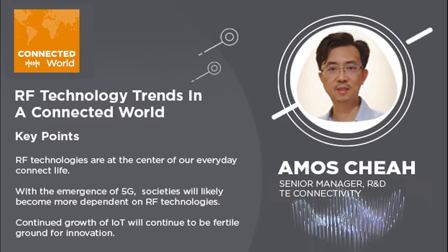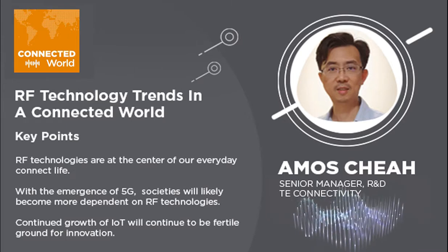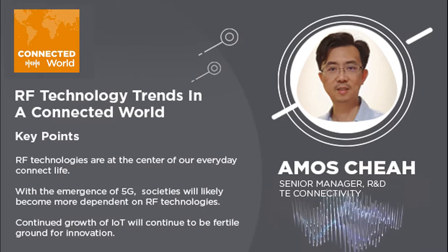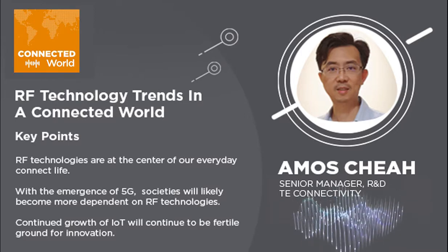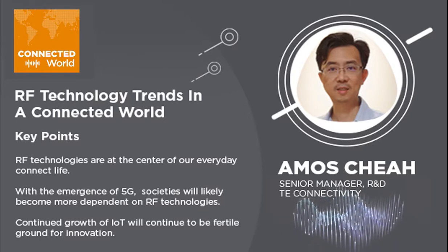EM RF signals, with a modulation technique and receiver circuitry, have the ability to transfer user signals over long distances. And lastly, no line of sight is needed. The only wireless communication medium that can compete with electromagnetic waves is light, but light is actually a very high frequency electromagnetic wave, which requires line of sight. But for RF communication, a clear line of sight is not required.